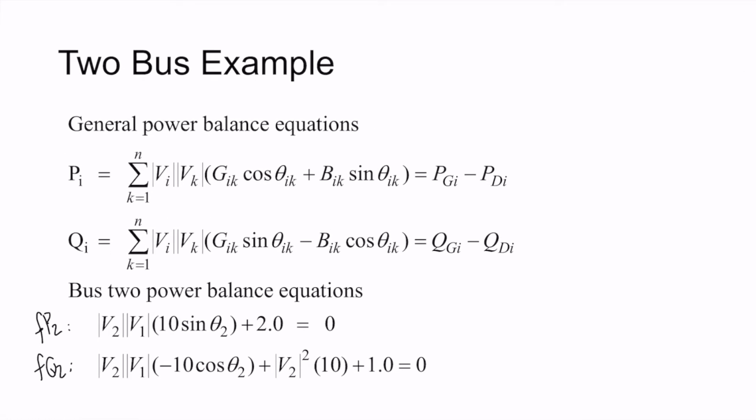Given the analytical expression for the net injection power in node i, I will just start to replace values. Then I need to use these equations to describe, in terms of the phasor of the voltage, the active and reactive power at node 2. So at node 2 it will be V2 times V1.